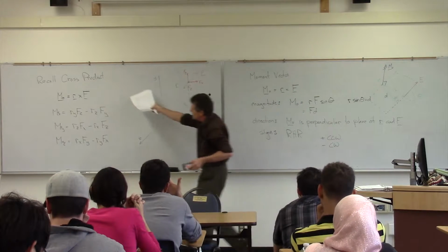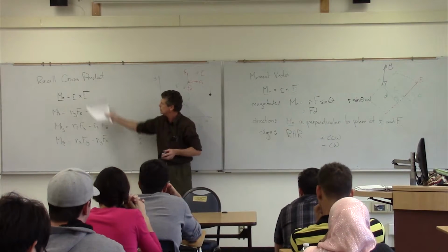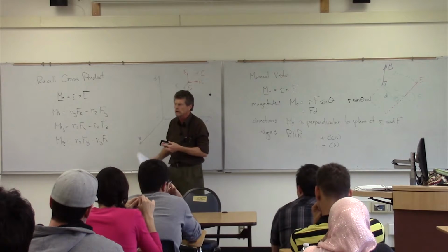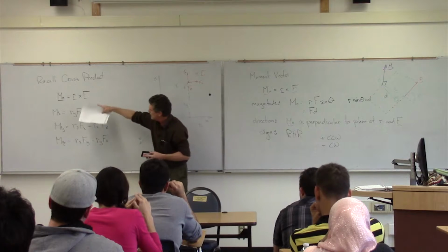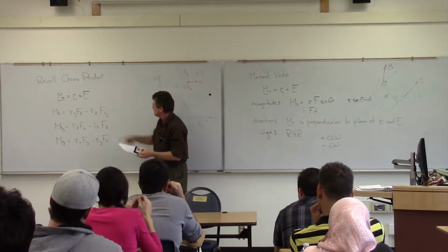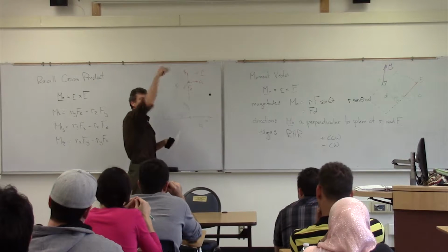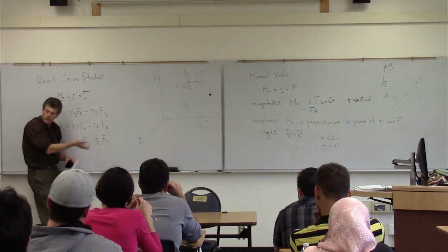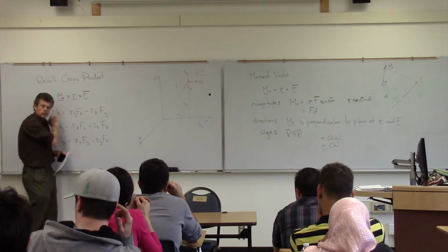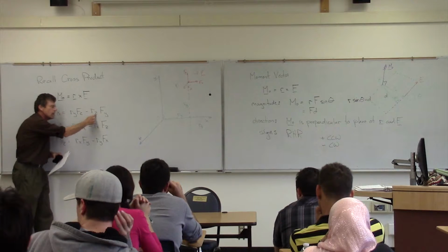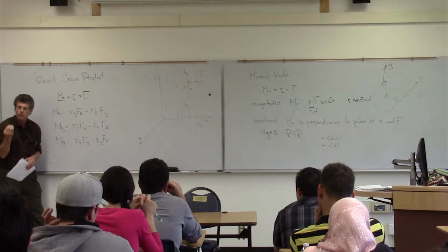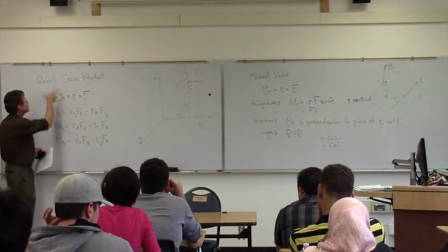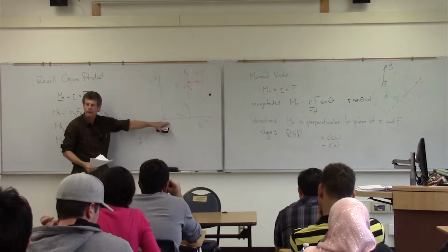So that's basically when we plug and chug and go through this cross product, what it's really doing is simply summing up all of those x and y components. It's very nice, it's straightforward. And again, the signs take care of it. Again, I said the f of y was going this way. Well, if f of y was negative, the negative will cancel with this negative. We'd end up having a positive twist. So again, the signs will take care of themselves as long as you pay attention to those signs. Make sure your position vectors are described correctly and your force is described correctly in the Cartesian system that you set up.